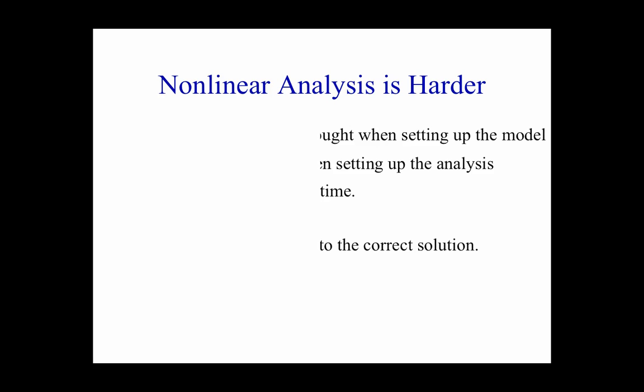And even though it does converge, you are not guaranteed that it's the correct solution that it's converged to. You will get answers. When you get answers from nonlinear analysis, always go in and check the answers. Do they make sense? Professor Mahan is not here today. He gets money consulting, just going around looking at people's models, seeing what the output is, and he knows if they make sense or not. It's a skill you need to develop as graduate students. But you really have to look at these results and ask yourselves, do they make sense?